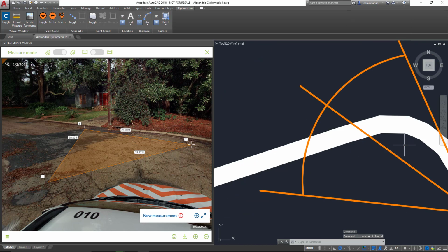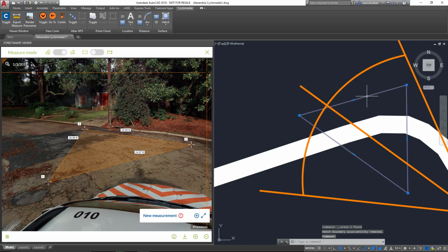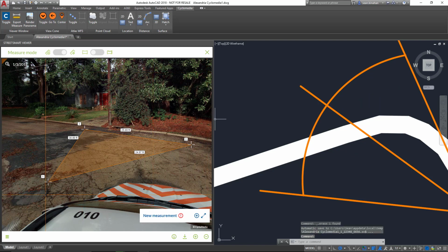Delete that. And we'll just try that again in 2D mode. And there you have it. So either way, the reason you get that little warning there is just so that you aren't surprised when there is no z-axis. Other than that, these points do have an elevation information to them. They do have a z-axis, so exporting as polyline or polygon mesh will retain the elevation data of these points.